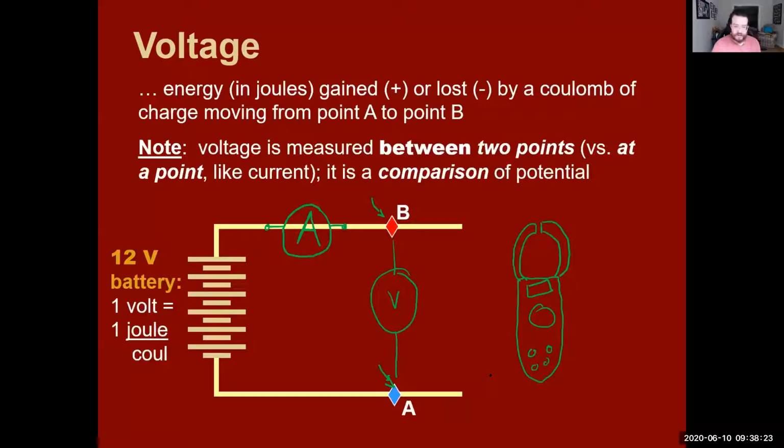This claw on the metering device is used to find your current, because it uses a couple different readings. I believe it's using the electromagnetic field coming out from the wire to calculate current. So you don't have to have it in line. You can actually clamp it around a wire and get its actual amperage.